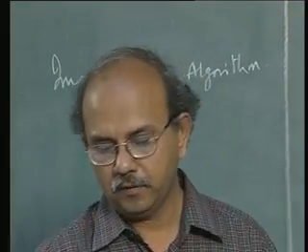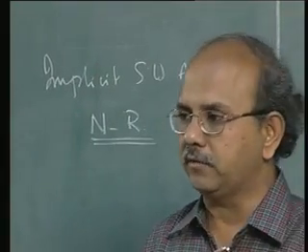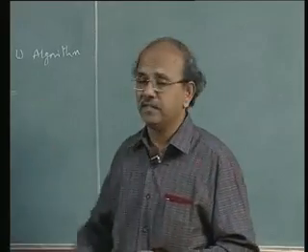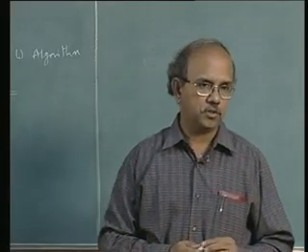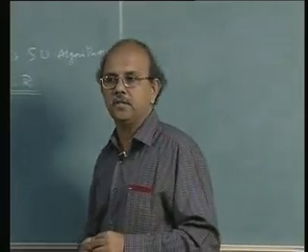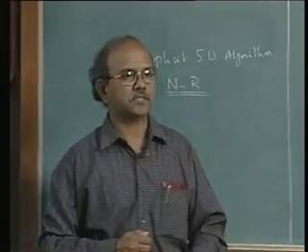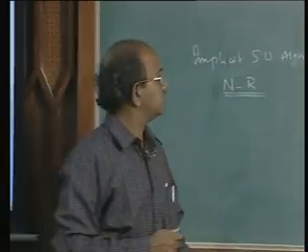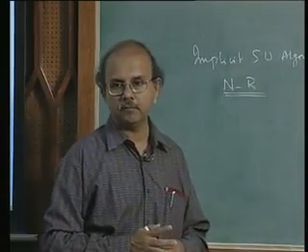So, and again, as the name indicates, we may have to then follow what is called as the Newton-Raphson scheme. The procedure that I'm just going to indicate is due to Simo and Ortiz, paper which came out in 1986 in International Journal for Numerical Methods and Engineering.